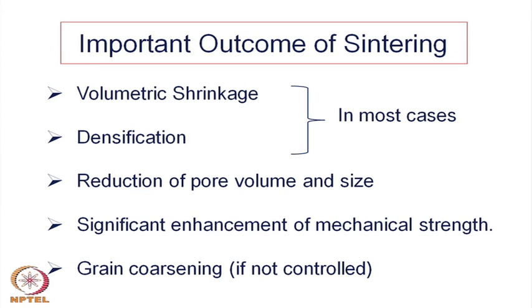Sometimes the grain growth is good for certain purposes, but particularly for mechanical properties, grain growth may not always be good. So, you need to control that aspect also. So, these are important outcomes of the sintering process.